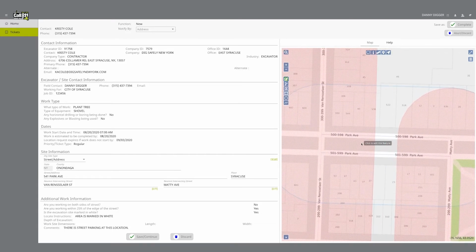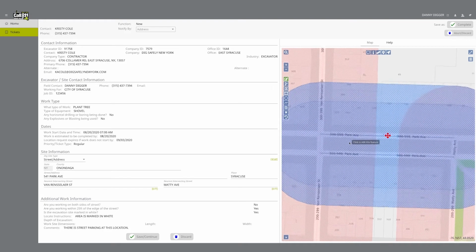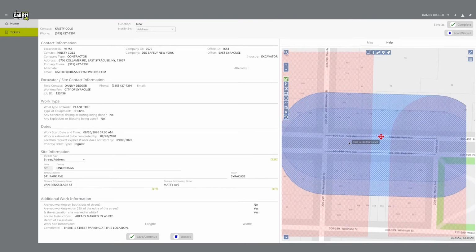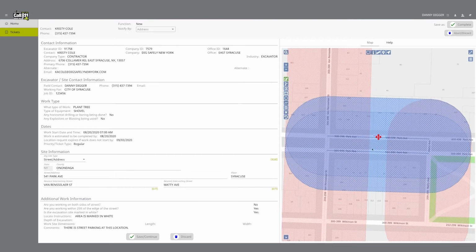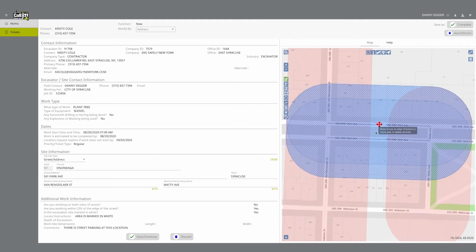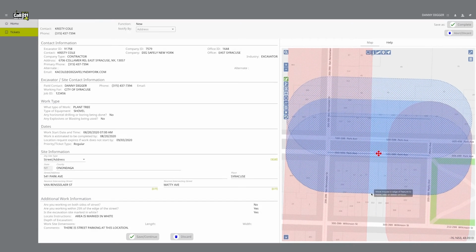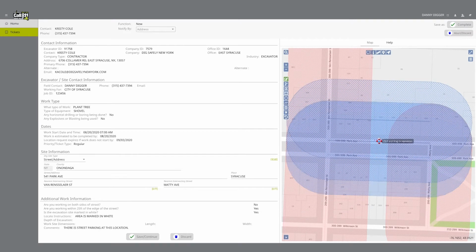Hover over your blue dig site with your computer mouse and follow the prompt to click one time. Clicking will turn your blue shaded dig site into a gridded, hash-marked blue area. And you will have 3 new icons on your screen: Save, Cancel Discard, and Undo. If you click on the outside line of the now gridded dig site area, you will have the ability to expand your gridded area or manipulate the shape of your dig site.